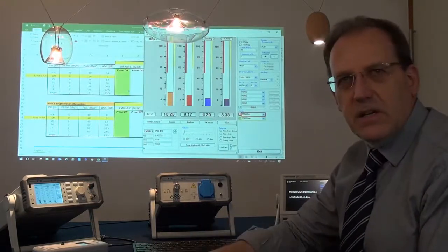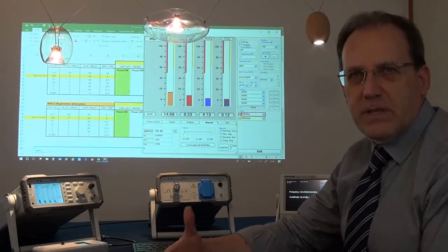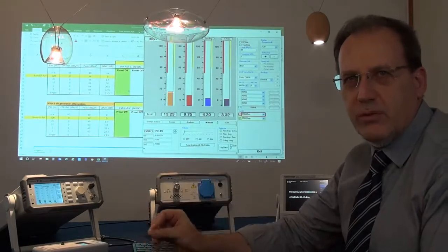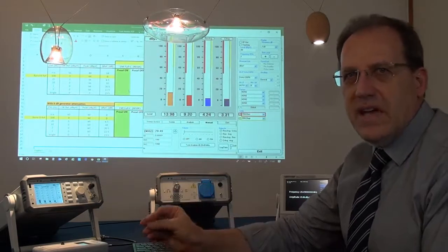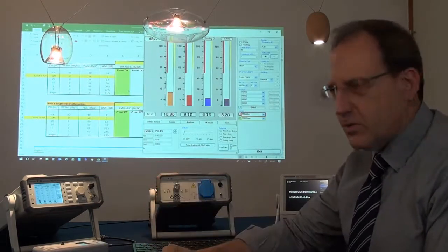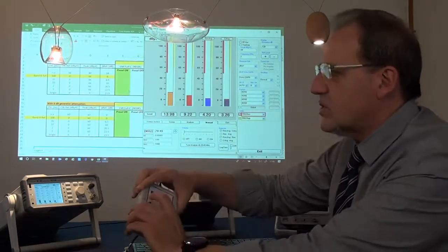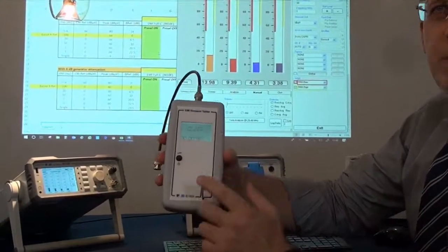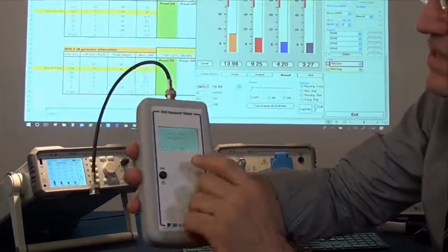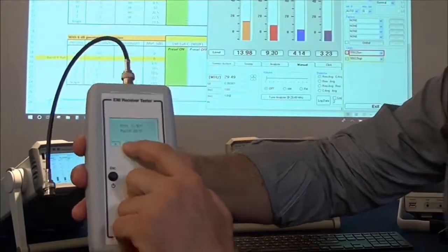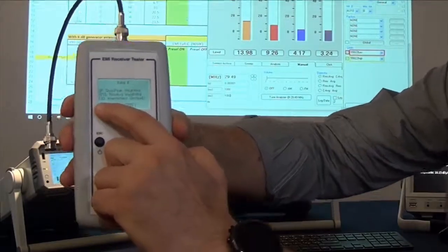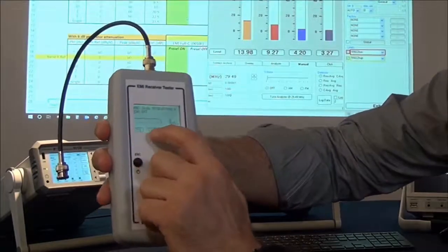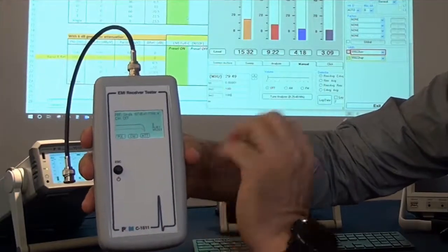So as we have discussed before about the importance, the relevance of the preselection, this kind of practical demonstration is very helpful to show how this is acting in reality on these different units. To show this, we will use a pulse generator that is exactly providing us all the pulses that we need to perform this kind of test. You can see here we can select the band. We will use the band B for Q-peak detection, and of course we will use both the pulses and the carrier wave to show how these are measuring.